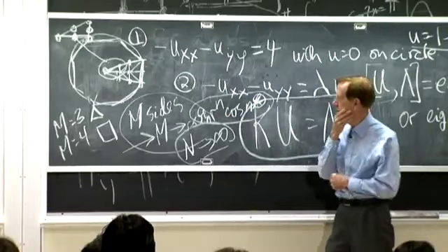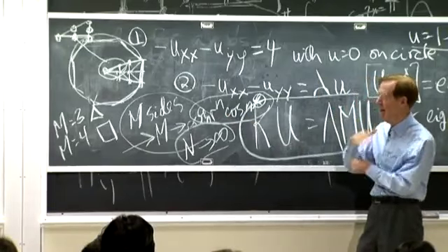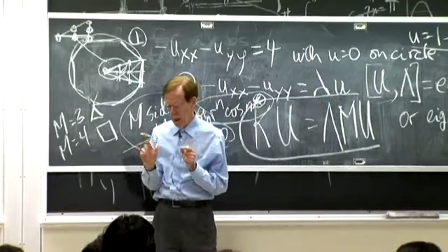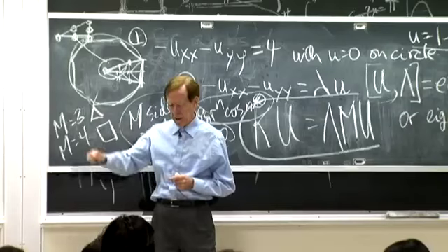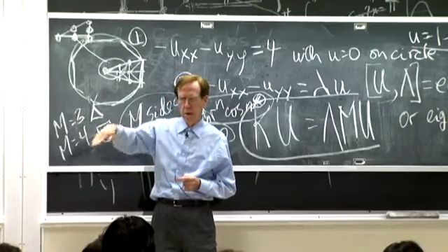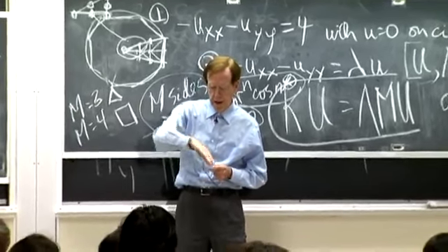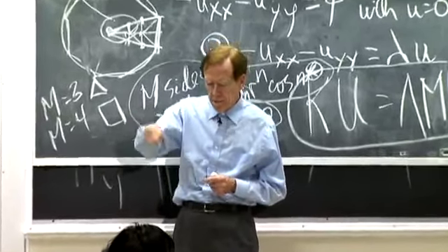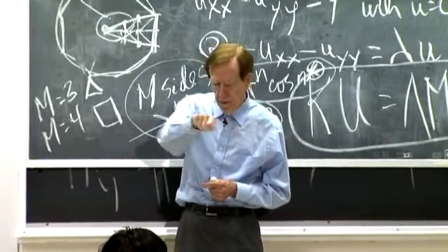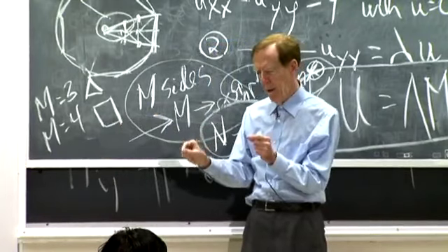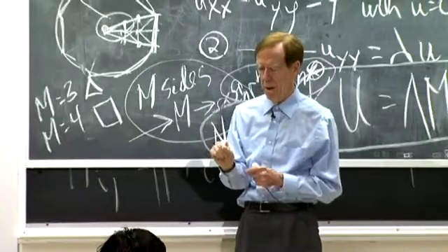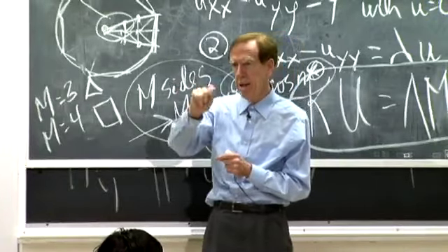And it's way bigger when r is 1 and way smaller when r is 0. So that's my theory. Physically, if you have a circular plate and you're maintaining the boundary temperature at some sort of oscillation, near 1 but up and down from 1, then further inside it hardly knows about that oscillation.